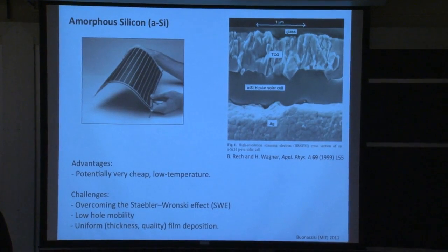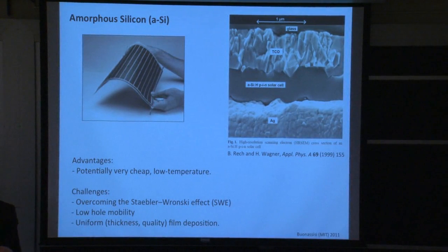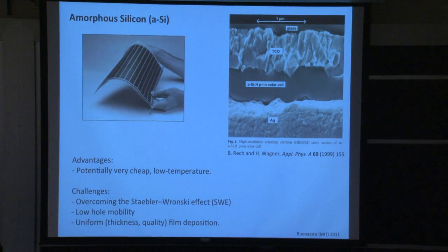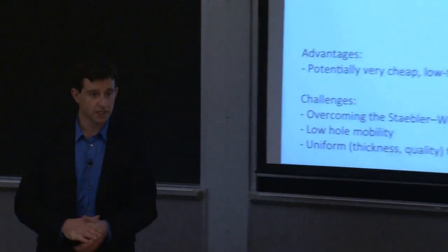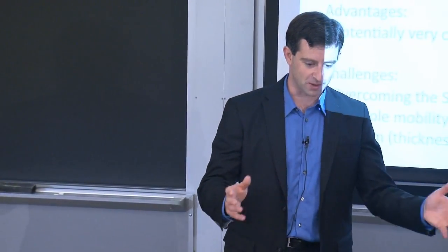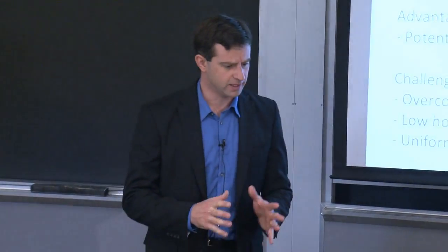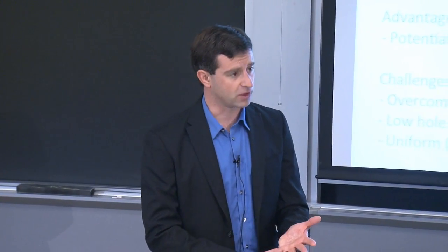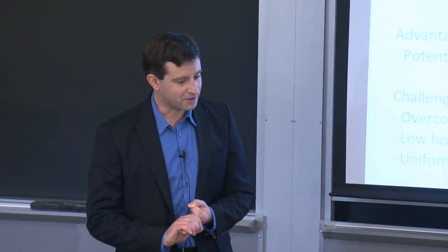Amorphous silicon, on the other hand, is a very broad term catching a range of materials that lack long-range order. Let me be a little bit more specific. Typically, there is some semblance of short-range order in these materials. One can describe the composition of amorphous silicon using, for example, a radial distribution function, the average distance from one atom to the next, and you have these distribution functions describing the material. It gets a little bit more tricky when you try to define it on a more detailed level with average number of nearest neighbors, the local configuration, the number of stretched bonds locally.